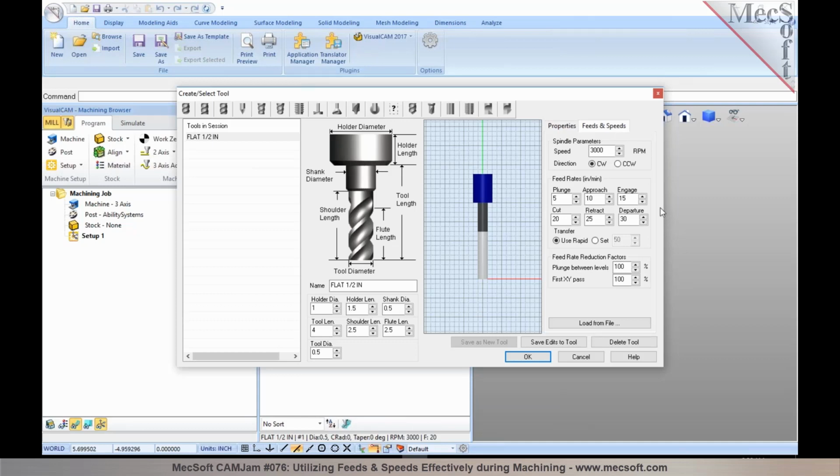So now when you create a new machining operation, it's automatically going to load the feeds and speeds that you defined on the tool. So this saves you a significant amount of time having to rekey each of these parameters as you program machining operations in here. So you could take advantage of defining your tools, establish your feeds and speeds, save them to a library, and loading the library will automatically reload the same library as you create new programs for different types of parts in here.